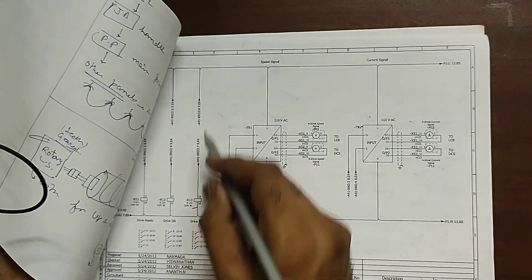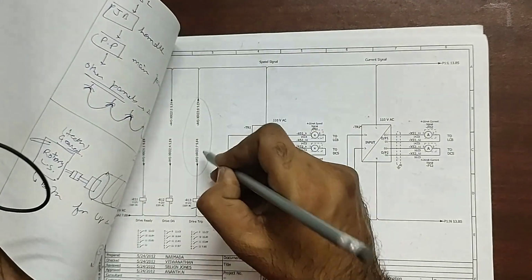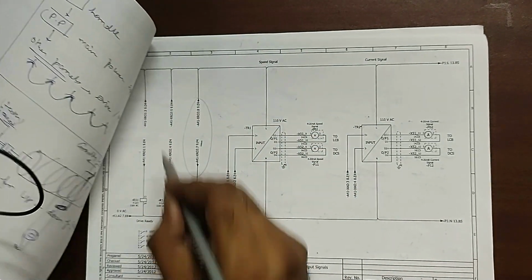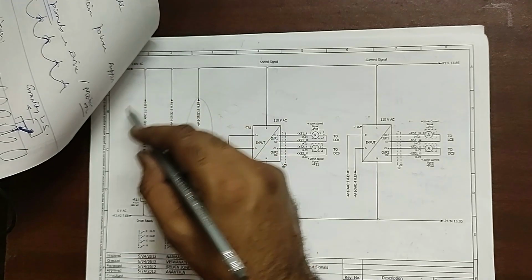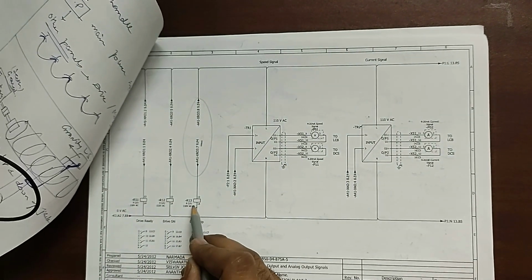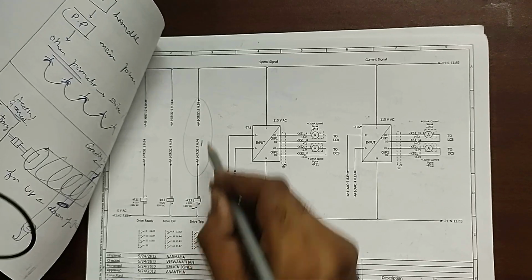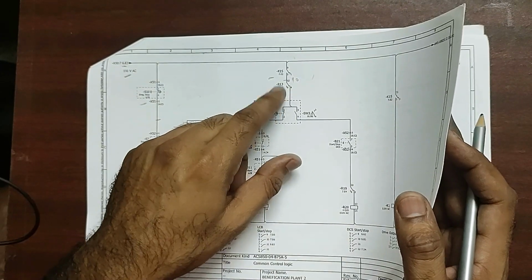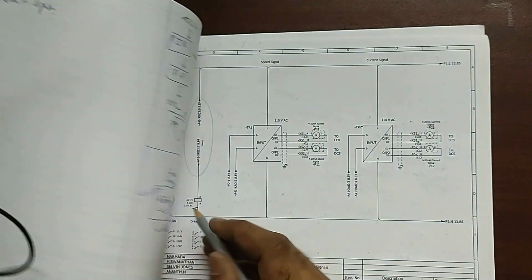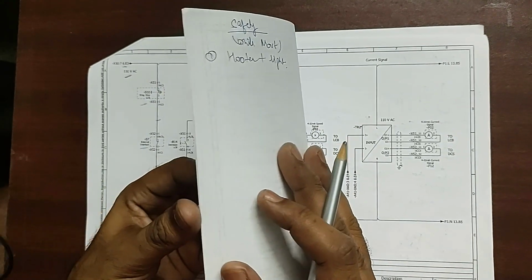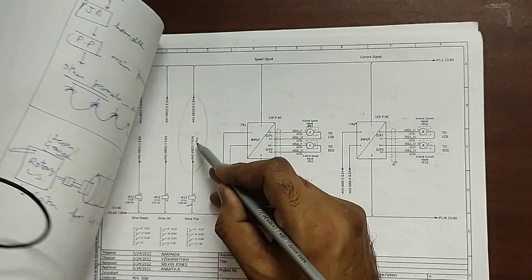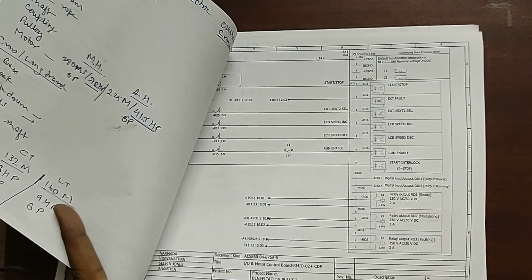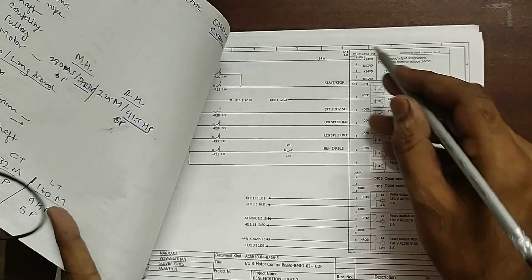Okay, R13 is here. So this command is coming from the panel, from the drive. Here you can see, it will get high, all these three will get energized once the command comes from the drive. In this condition, this will get high or low as per the settings in the panel. Okay, so this has to remain NC, no? So that means R13 should not get high, and for that we'll have to go to page number 9, because here it is written 9.F4. This is 9.F4, 9 F and 4.